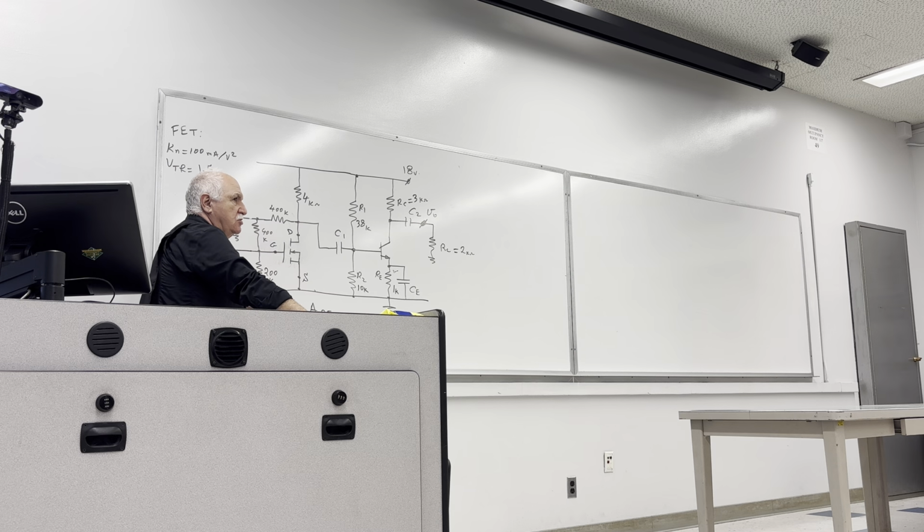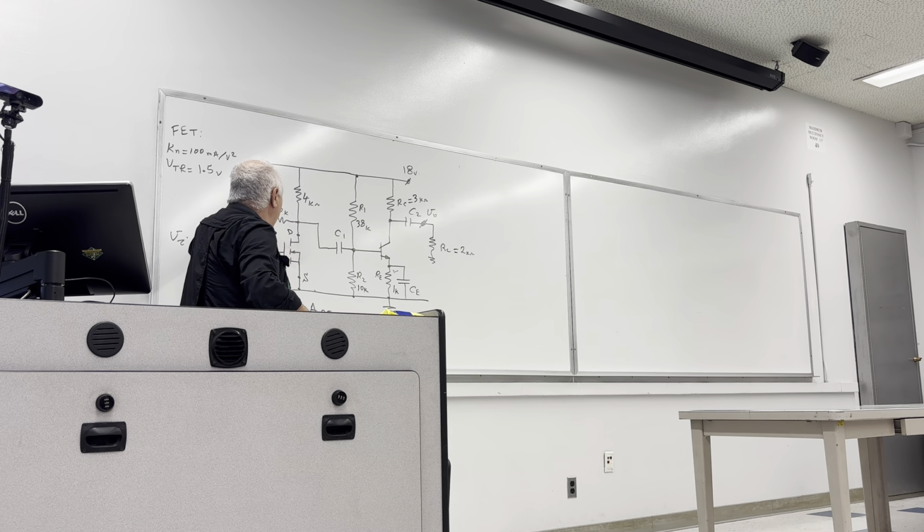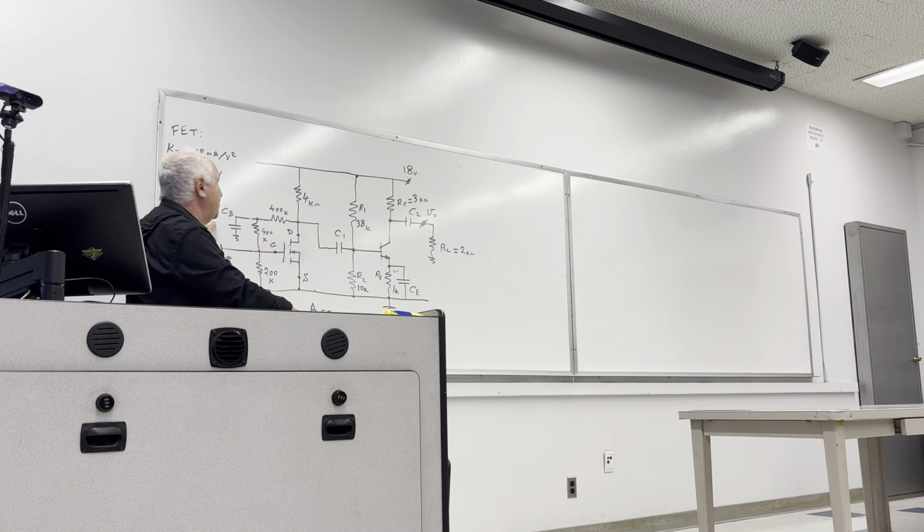We're not going to go into the feedback. Or if you want, remove that capacitor and reassess the voltage gain of that stage with the effect of the feedback in your AC model. You can do that. But that's not the intention. In here, we want a full common source voltage gain out of that stage number 1. So how do we kill that feedback or bypass the feedback?